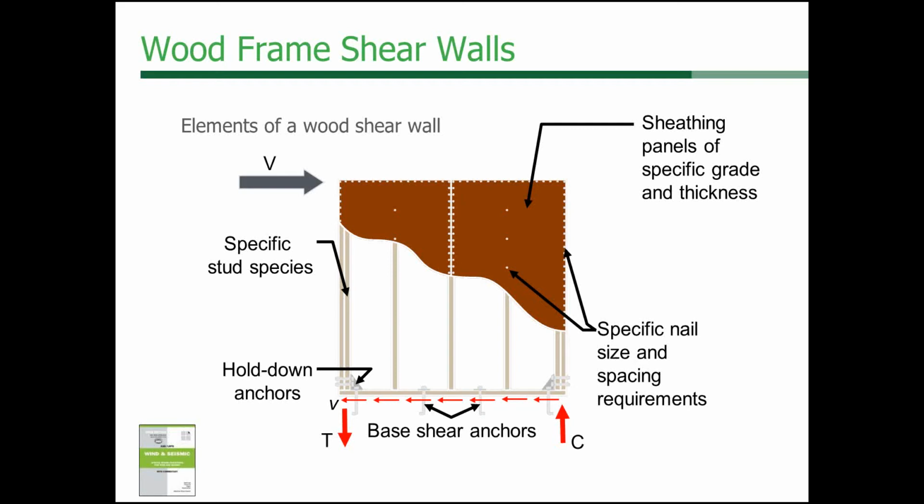Now this is an important thing to remember because the nails and the sheathing provide the ductility to your building, and we'll look at that in a minute. So something to think of. That's what provides the ductility in a wood system, in a wood building.